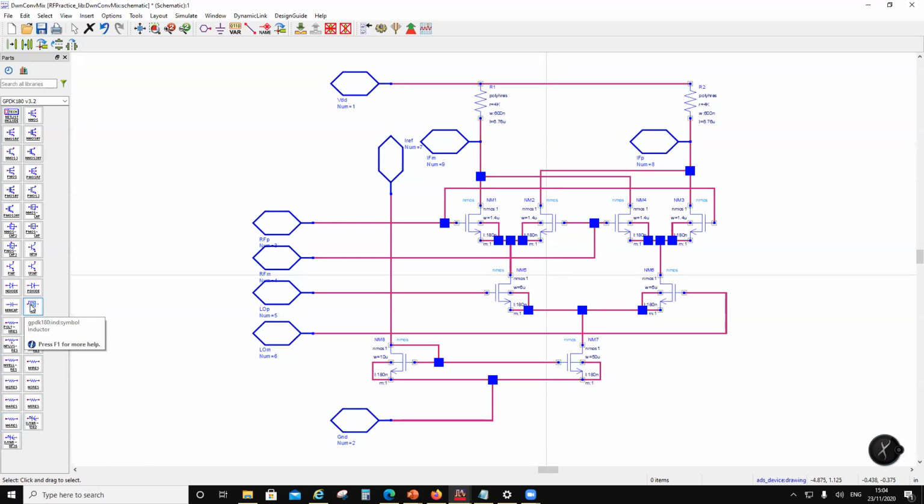Other than that, I haven't validated this inductor model. I haven't validated the capacitor model. I haven't even touched them. I have done various simulations on bipolars, but I'm not happy with them, because I cannot even simply generate a Gummel plot for this NPN. It was a totally absurd Gummel plot.